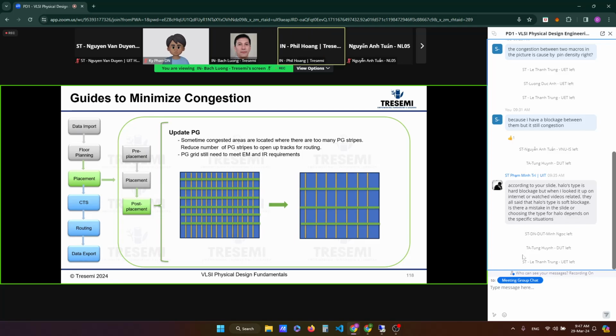Yeah, I want to add to that. We covered during floor planning early rail analysis, and it is strongly recommended that early power analysis be run to avoid over designing, and to make sure that if we are aggressive in terms of power grid, meaning that we don't over design, then we don't under design.